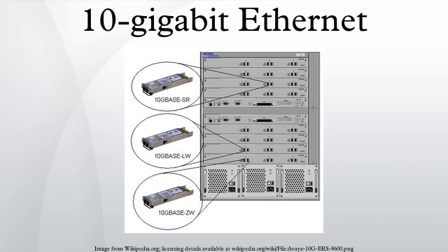10GBASE-ER. 10GBASE-ER is a port type for single-mode fiber and uses 1550 nm lasers. Its physical coding sublayer 64B/66B PCS is defined in IEEE 802.3 Clause 49 and its physical medium-dependent PMD in Clause 52. It delivers serialized data at a line rate of 10.3125 Gbits. The 10GBASE-ER transmitter is implemented with an externally modulated laser. 10GBASE-ER has a reach of 40 km over engineered links and 30 km over standard links.